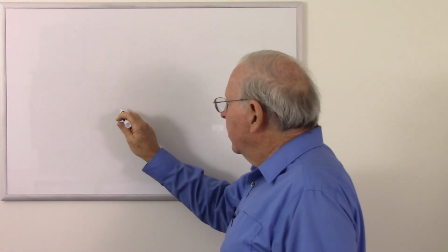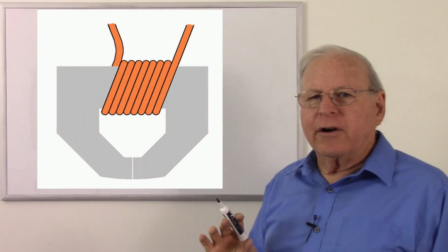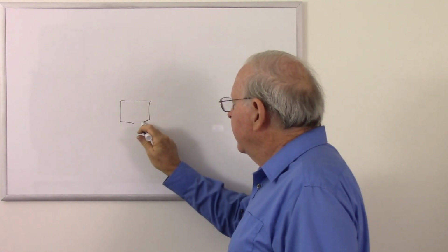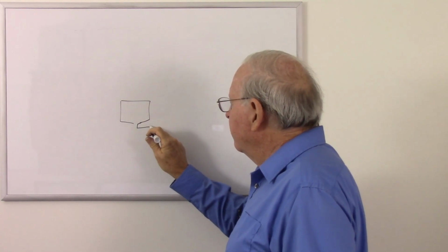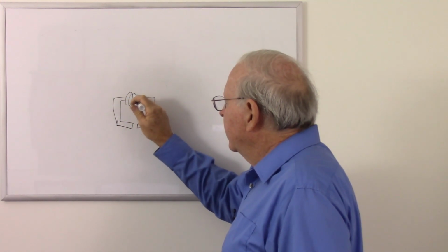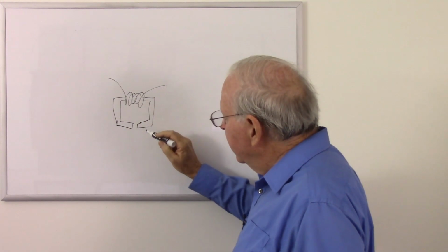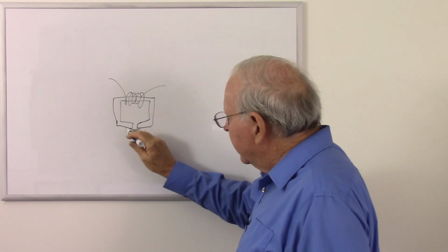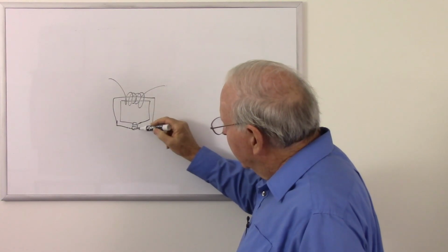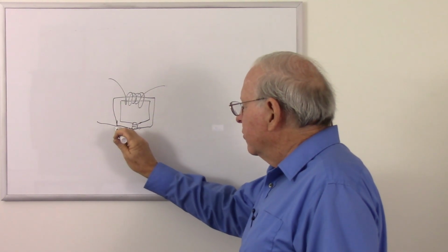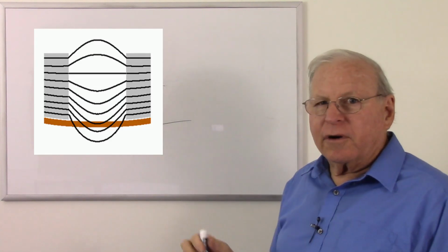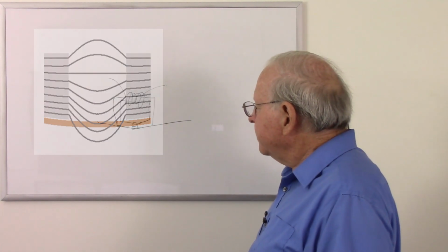So let's look at one of the recording heads. Here's a drawing of one here. I'll redraw it down here. Basically, we have some iron with an oversized gap, and there's a coil of wire coming in here that we can feed that, and of course we have the gap there because that's where the magnetic field comes out from between the iron poles there, and as the tape goes across there it magnetizes the iron oxide or whatever formulation we have on that tape.